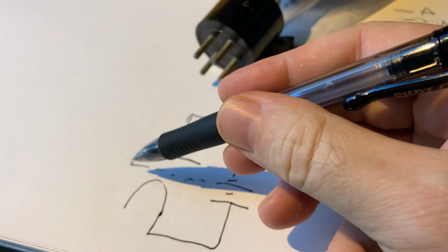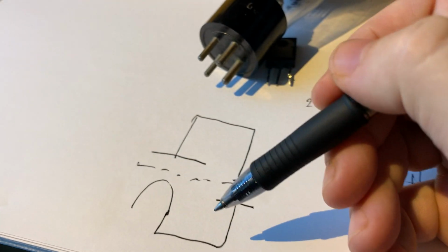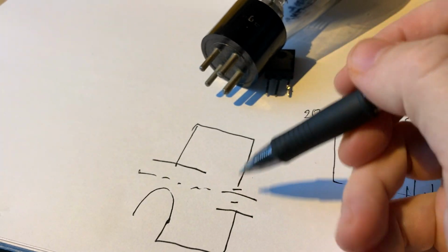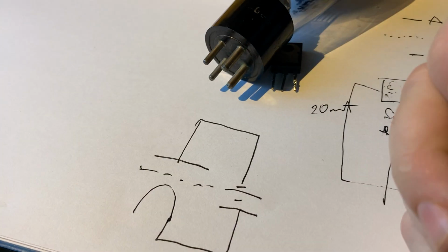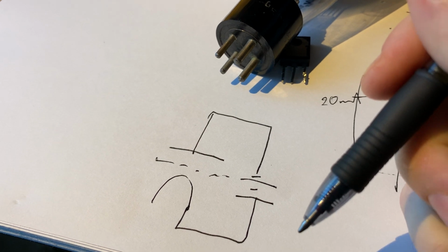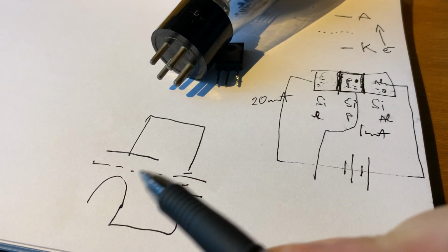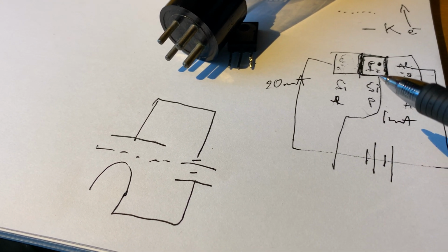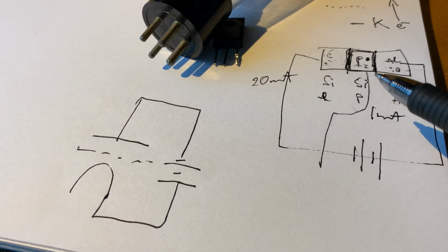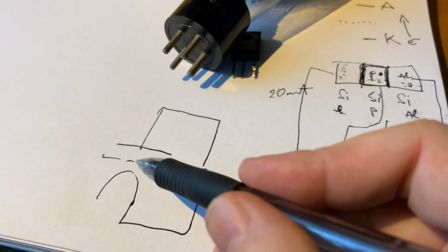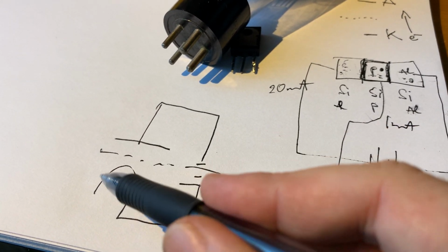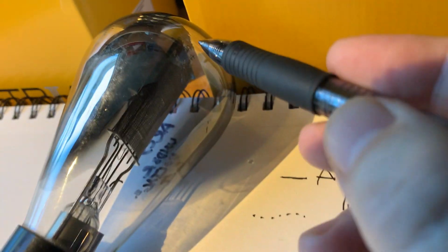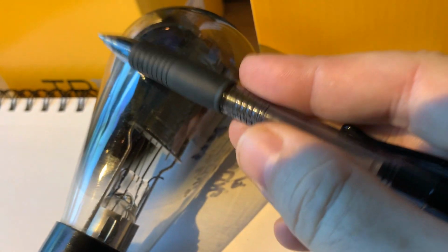So based on the voltage we apply to this control grid, the current either flows or it's cut down. But let's see what's the difference between this situation and that, because until now it seems that the tubes are doing the same thing as a transistor. However, the huge difference is that here, these three elements are not physically connected. They are separated from each other and they are inside a hard vacuum.